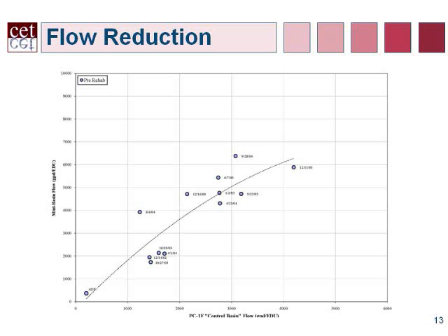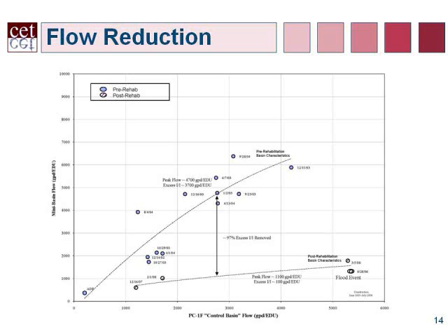Another crucial use of the basin characteristic curves is to demonstrate the effectiveness of rehabilitation. Once rehabilitation efforts are completed, subsequent wet weather events can be metered. These new points can be used to develop a new basin characteristic curve for post-rehabilitation conditions. When plotted together, the difference between the curves represents the level of excess I&I that has been removed. This can easily be coupled with rehabilitation costs to establish a cost per gallon of removal. This cost ratio can then be used to evaluate various rehabilitation methods or treatment options to effectively select the most cost-effective solutions.